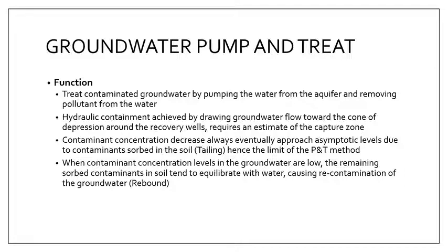Alright? And the coverage area of a groundwater pump and treat method is dictated by the capture zone of your treatment well. So this capture zone is approximated by your cone of depression. Alright? And it might be necessary to use multiple wells to ensure that the capture zones of your wells are actually covering your target contaminants.